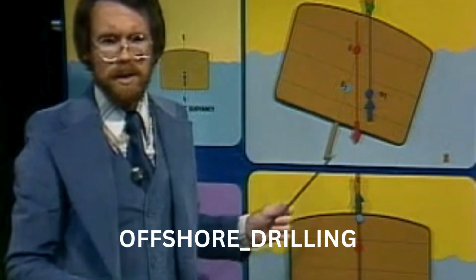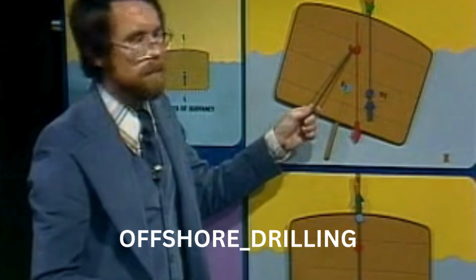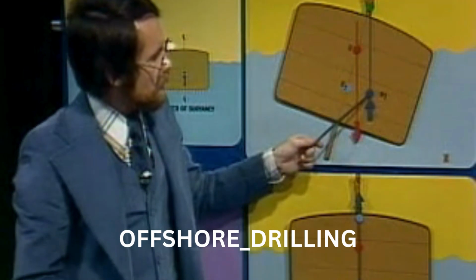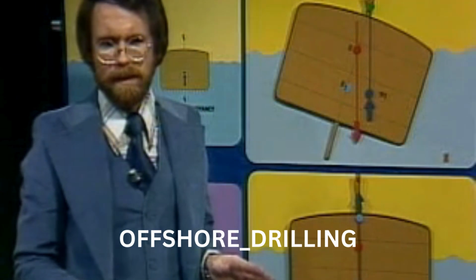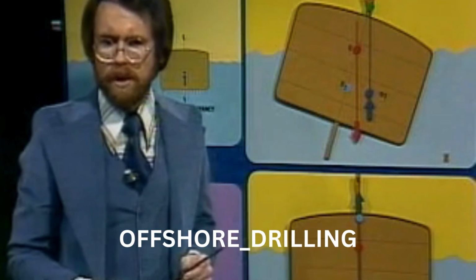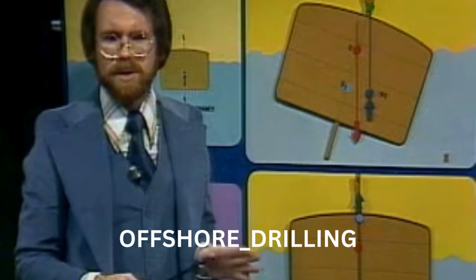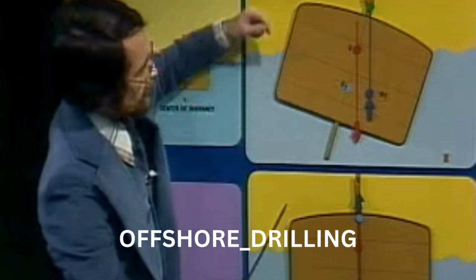As we can see here, the force of gravity works downwards through point G, the center of gravity, and the force of buoyancy works upwards through B, the center of buoyancy. Because these 2 points are separated, a couple is created, which in this case will cause the vessel to return to its original upright position.